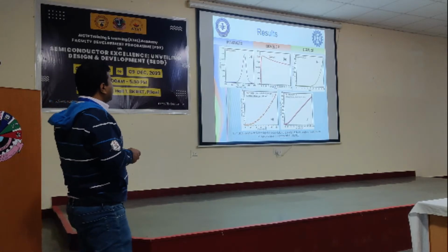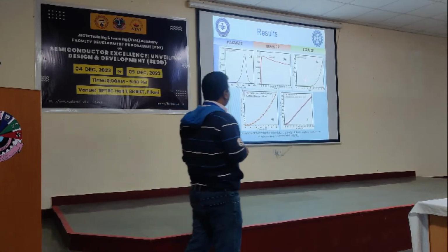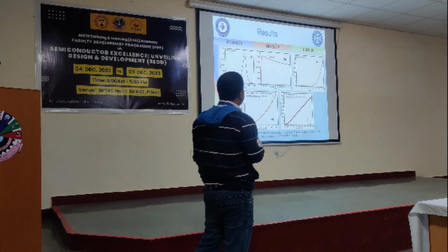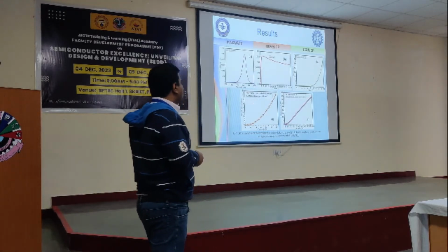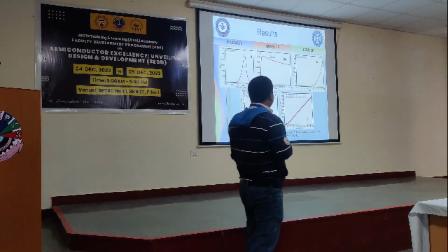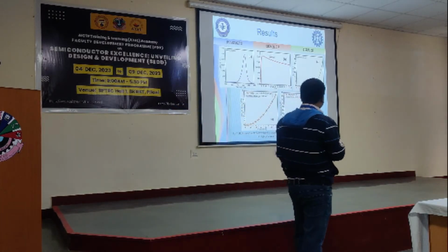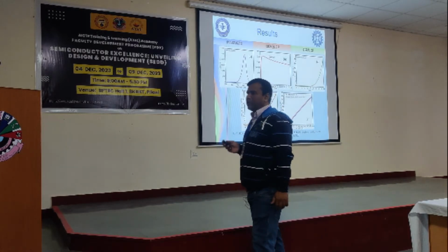Now this is the internal quantum efficiency, 25%, and the turn on voltage achieved is 5.2 volts. In the two cases, output power is there for both electrodes. Where the finger electrode is taken, the power is in the range of 4.9 milliwatt, and when you take the electrode in a circular pattern, in that case your output power will be quite high.